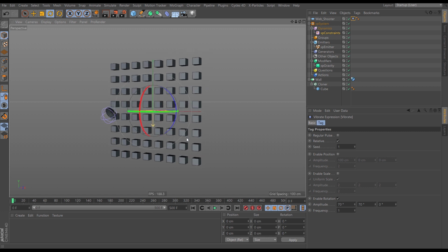So what we will do is we'll move on to doing a quick render with Cycles 4D on this. Before we do, let's get it cached out. So I'm just going to do a very, very basic cache here. Let's go to... oh, actually, no, before we do that, I've forgotten one step, which is crucial. Now, constraints can't be rendered, but the only thing we want to render are these springs between particles. This is going to be our spider's web. So how do we do it?